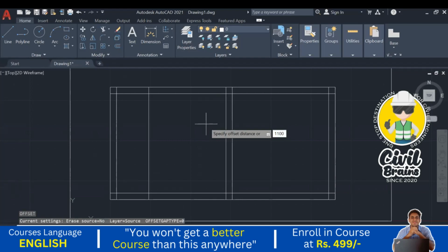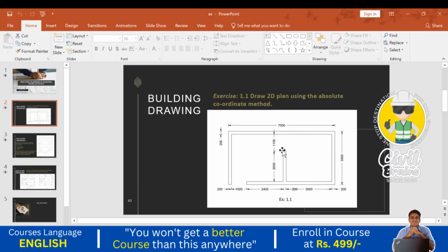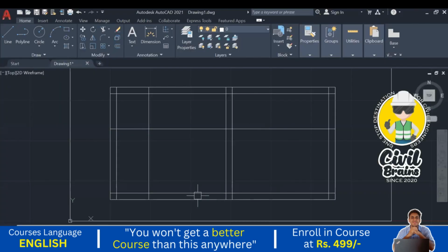Okay, so I just confirm this one. Here you see 1000 and this one is 1100. Clear? So now what is next? Once you've done this, the next command is for whatever extra lines there are. Those lines we need to cut, or delete, or trim. So for that we have the trim command.